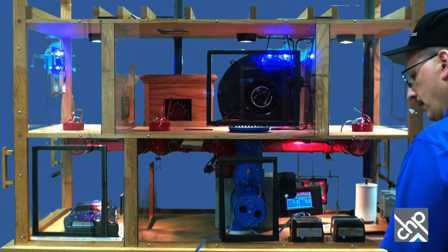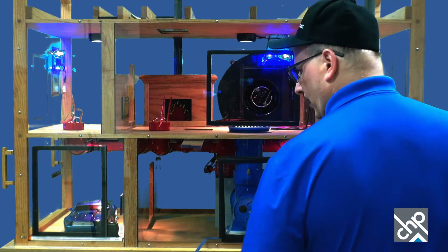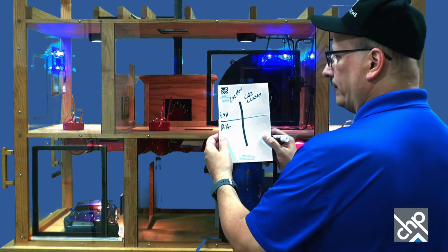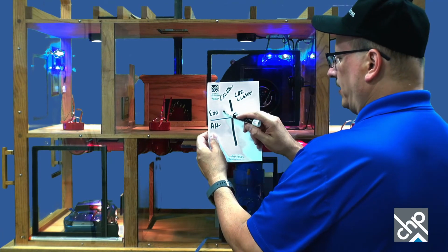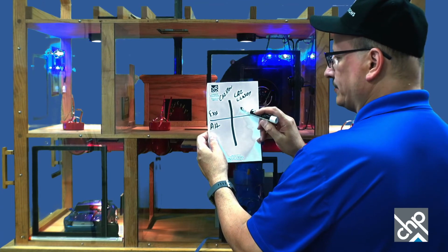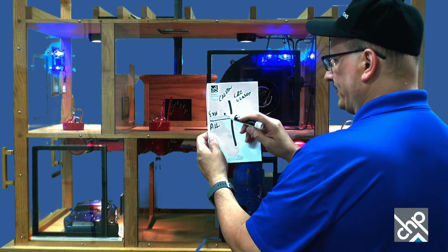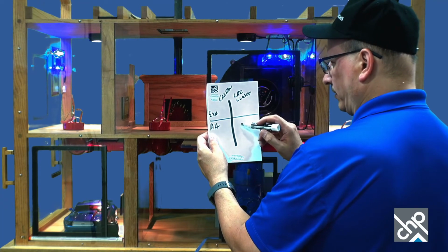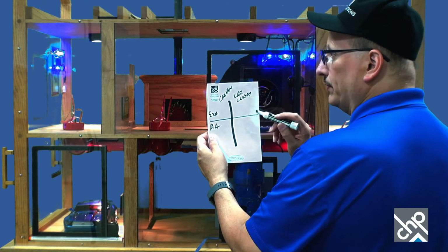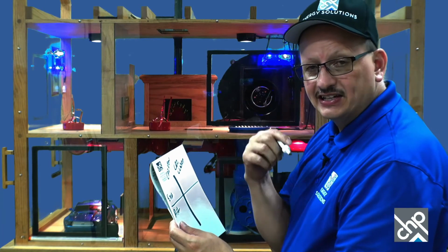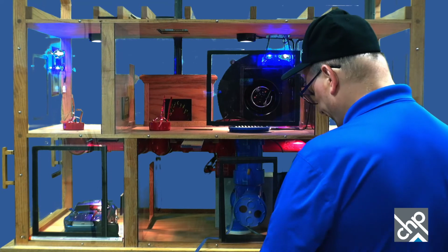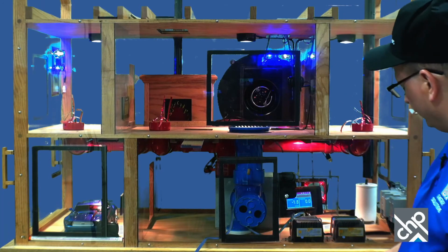All right. So I might even try writing them either on a piece of paper or on the house. We'll see how that goes. So I got a little piece of paper here. So basically, we're going to have 4 numbers there. So exhaust with the CAZ door open, exhaust with the CAZ door closed, air handler, where exhaust fans are still on, with CAZ door open, and then the air handler with CAZ door closed. And you're going to take the worst one of those. That will be your worst case CAZ, and you go back to that setup when you do your combustion testing. All right. We'll fill those out as we go.